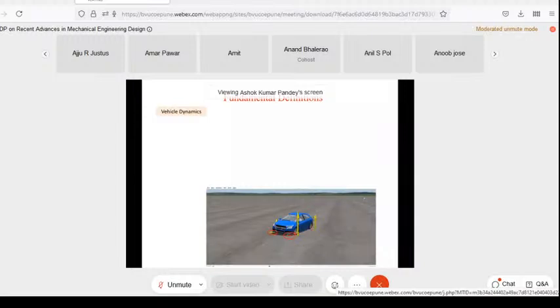So these are the forces that exist, and all these forces are dependent on the normal load which exists. So if the normal load at the wheel reduces, these forces will also reduce. That is the influence that will happen, and you can see that as your vehicle is turning, all these forces are oscillating. Here you can see, I think from here this is quite clear.